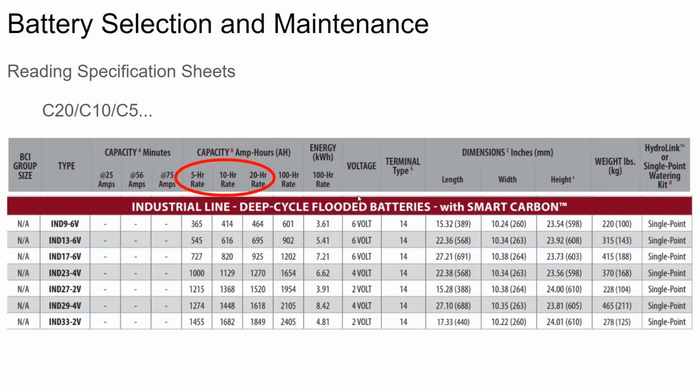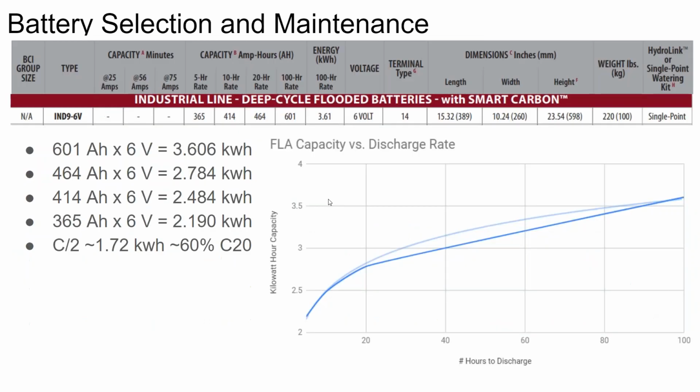The problem with doing that is you're just going to generate a whole bunch of heat. And so that's where the amp hours are going. That's where you're losing it. Now, this is not the same as the batteries that were exploding airplanes out of the sky because they were getting too hot. That's a low-end lithium-ion issue that's separate from just generating heat with lead acid because you're discharging it too fast. Nobody's flying 4,000-pound batteries all over the world.